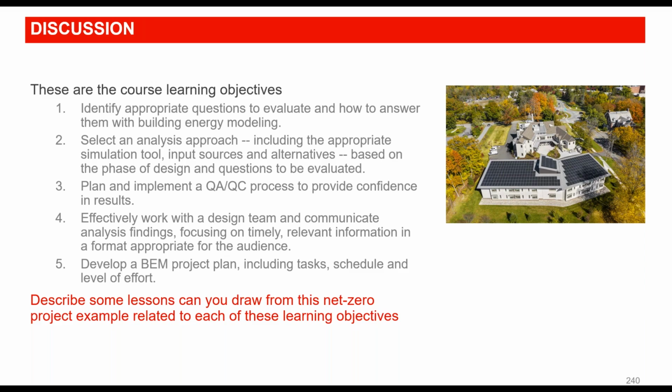And Sam, do you want to chime in about WUFI? Yeah, I guess it's sort of out of the scope of what we're going to talk about today. I think certainly for projects, making sure the dew point is outside, like doing a WUFI model to figure out where dew point will fall and where your vapor barrier falls, I think is critical. A little outside, I'd say, of scope of what we're talking about today, but.